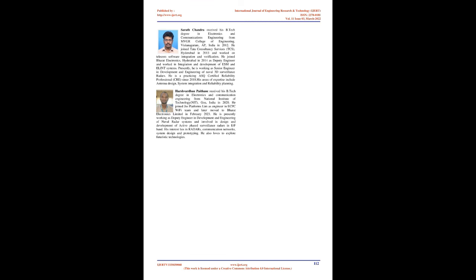Interestingly, 5.42 dB loss in beam peak gain is observed in CST simulation as shown in Table 3.4, for φmax equals 180° with respect to φmax equals 0° case. Though it looks like a many-fold reduction in gain, the actual effect on ranges will not be very large and will be compensated by thoughtful waveform planning and timing. Finally, a ripple of plus or minus 0.4 dB is observed for φmax equals 180° case, which can be comfortably factored under beam shape loss in radar link budget.